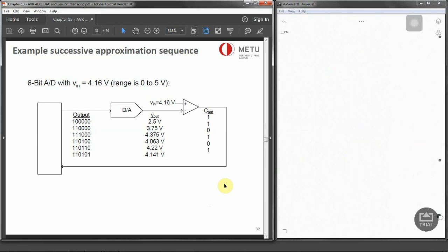In order to do that, we have got 5 volts equals the slope M multiplied by 140 degrees plus the intercept C, and on the other hand we have got minus 2.5 equals M times minus 10 degrees Celsius plus C.